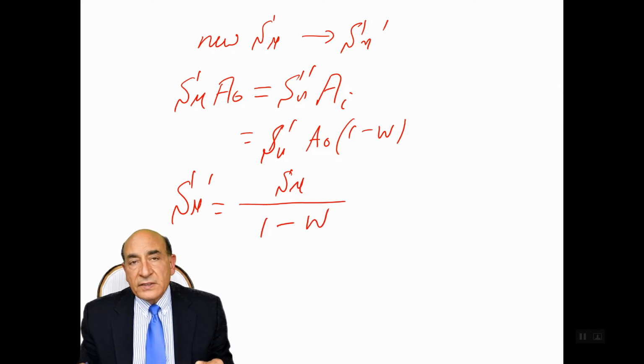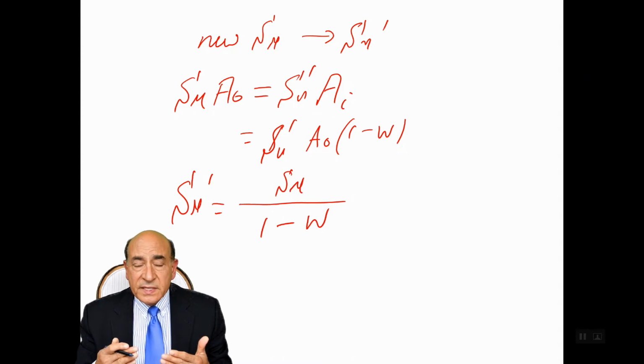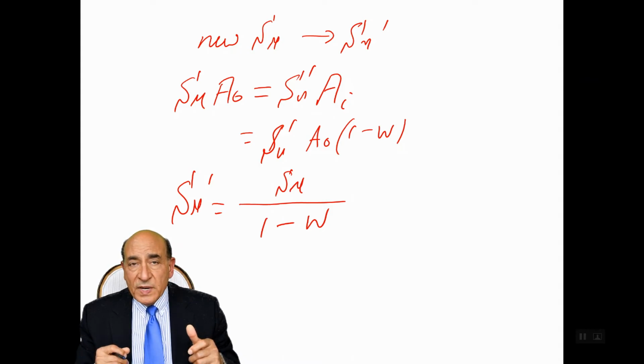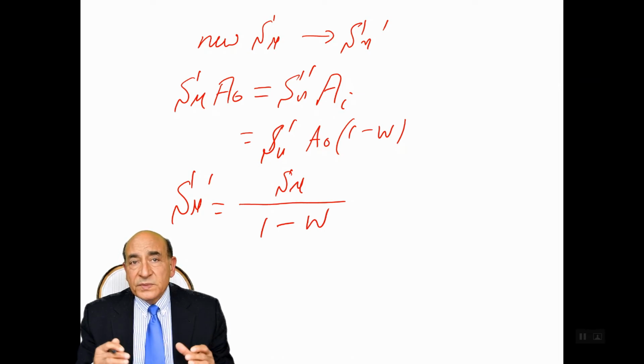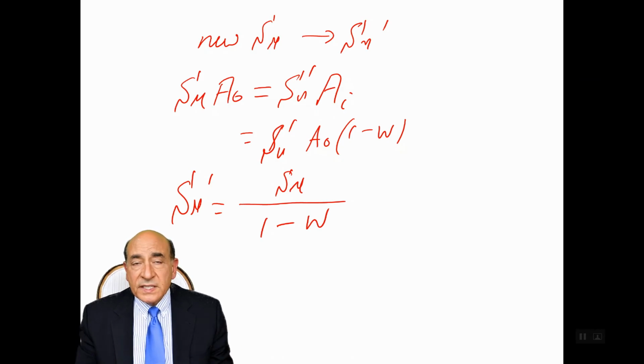So now we have one equation for the new yield, one equation for the ultimate, and it's important to compare them. If the new yield is very close to the ultimate, it means that we harden the material too much and it becomes not as ductile, because it wouldn't have a lot of work hardening capabilities, but it would behave as a brittle material. So too much cold work is not so good. A little bit of cold work may be good because it increases the yield point and the ultimate strength of the material.